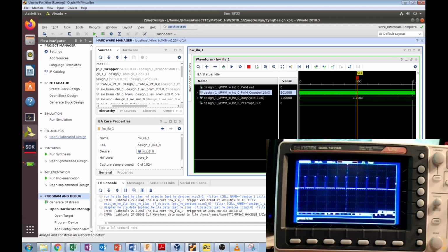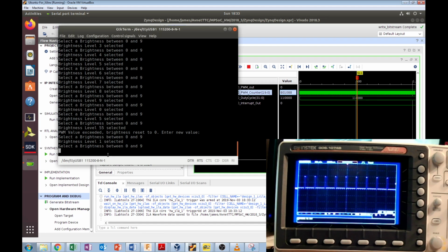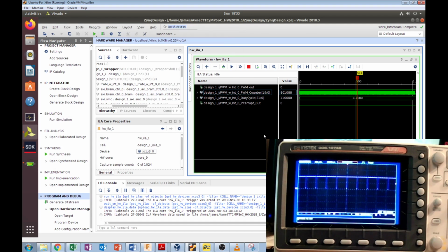Okay, and so once that's done, we're well into lab 8 now, so this is the logic analyzer and the Tcl command into the JTAG to AXI controller. Okay, so we can see all of that, and we can see that if I come into here and change the value manually, like let's say I put it to 9, we can see that this has updated, and I can manual trigger this as well, and that pulls in the new value right there.